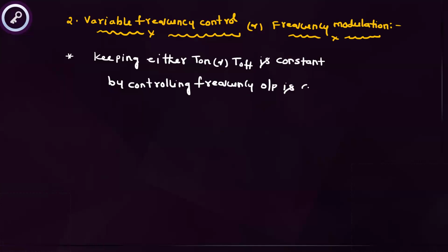But this method is not preferable as compared to PWM. Why? If you vary the frequency for a very large value, it causes the interference effect and a large filter is also required. That's why it is not preferred.